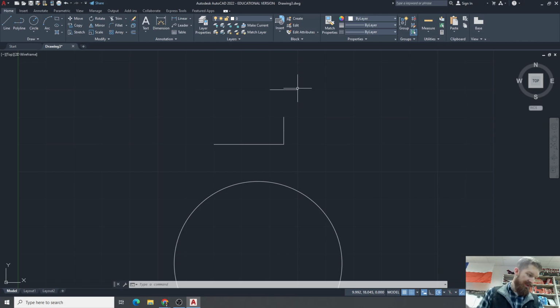Assuming you're planning to create only one viewport in the layout tab, so here's the layout tab, right? Set the PS LT scale, that's the paper space line type scale, and MS LT scale to 0, right? This setting of 0 forces the line type scale to appear in the same view layouts as in the model tab, so it just makes it 1 for 1. And you can set those just by typing them in.